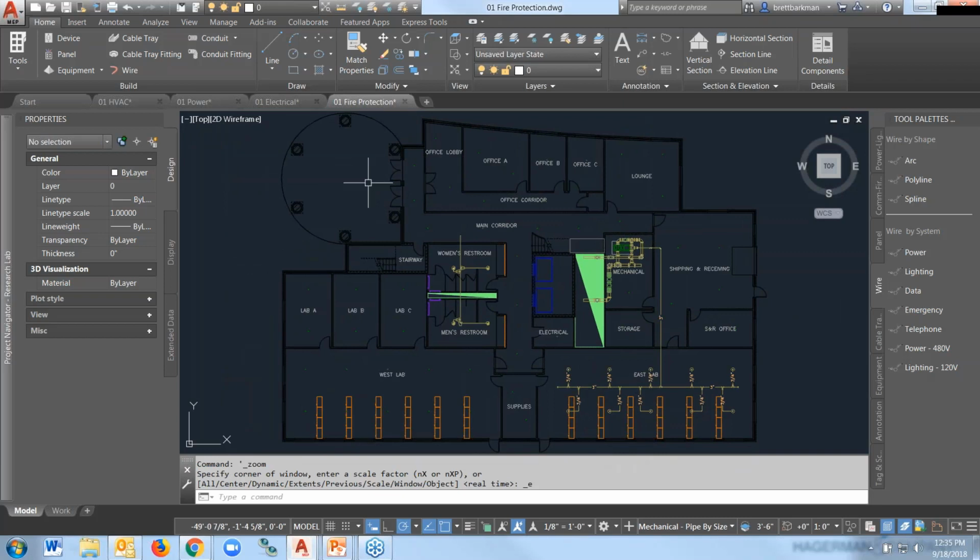All right, well, if there are no more questions, one just came in. Is there a shortcut to tagging CFMs for diffusers? Actually, there is. When you're tagging them, you would do that in a view in the project manager, like the architectural tool set showed with the different constructs and views. You create one, and when you tag the first diffuser, you have an option afterwards for multiple.